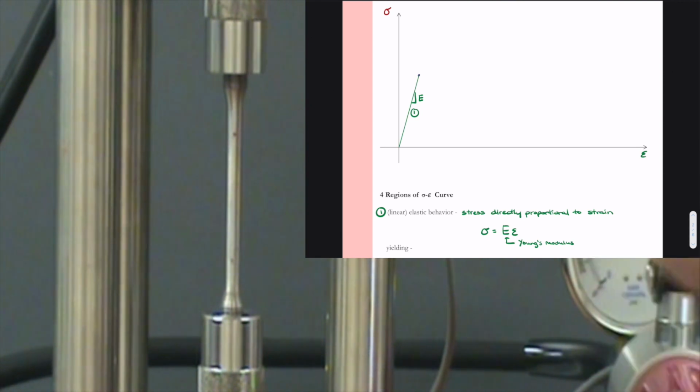And so yielding is the second region of our stress-strain curve for a typical ductile metal. Yielding is characterized by an increase in deflection without an increase in force, or in other words, an increase in strain without an increase in stress. Now, the stress doesn't drop to zero, it's just remaining constant, and you could hear me kind of stagnate around 26, 26.5, 27 kilonewtons, and that meant the force was remaining the same, even though I was continuing to pump the cylinder and stretch the material. This point is known as the yield stress, capital F sub y, and this is the stress at which the material starts to deform plastically.